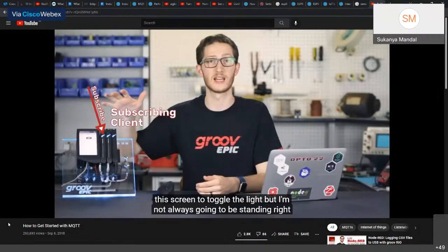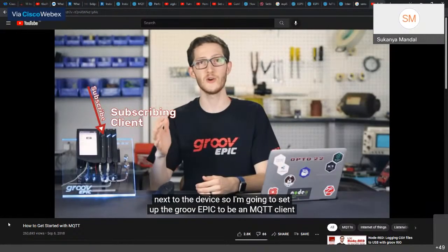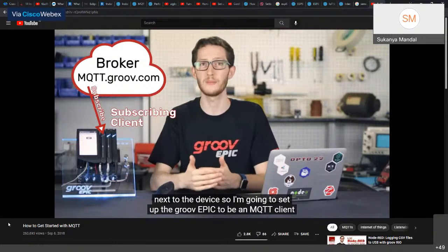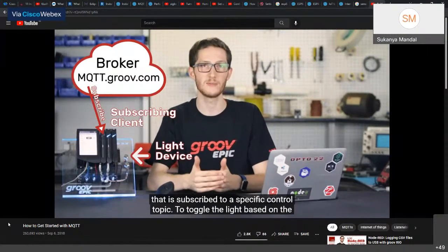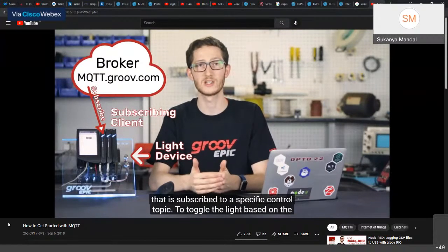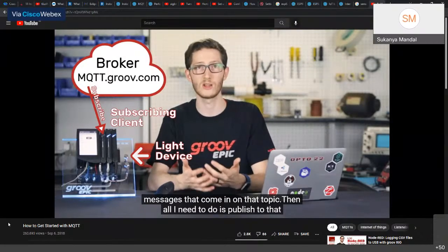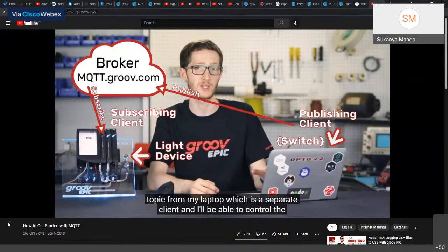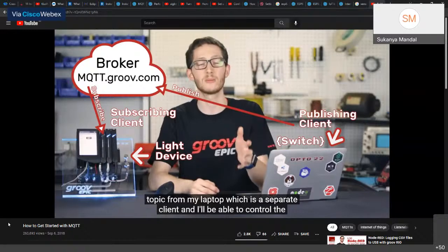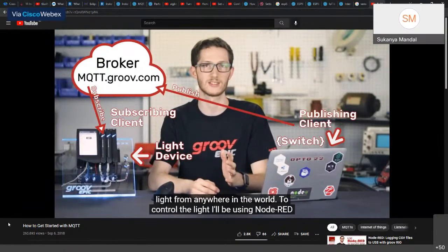I'm not always going to be standing right next to the device. So, I'm going to set up the Groove Epic to be an MQTT client that is subscribed to a specific control topic to toggle the light based on the messages that come in on that topic. Then, all I need to do is publish to that topic from my laptop, which is a separate client, and I'll be able to control the light from anywhere in the world.